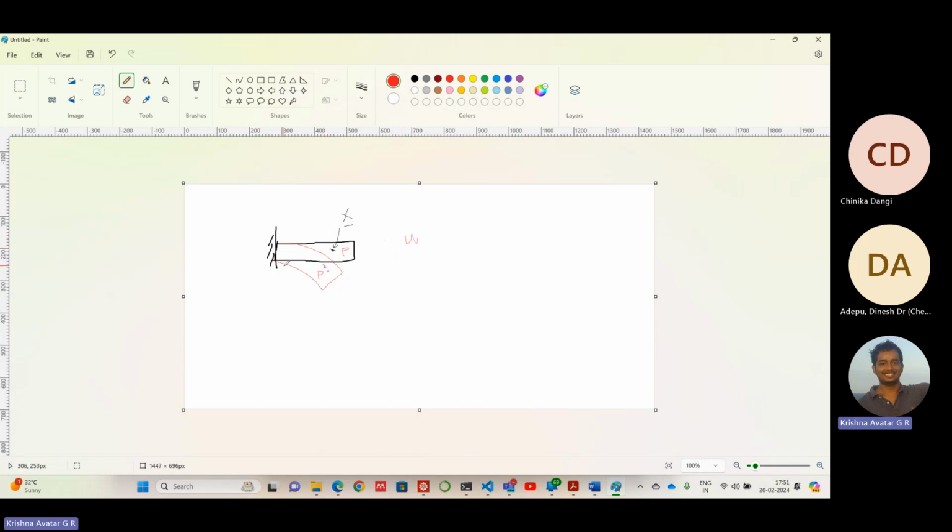The position vector of this in the Cartesian system will be x prime. So the relation between x prime and x is x prime equals x plus u. This u is the unknown. In the total Lagrangian formulation, we always work in the reference configuration, and our goal is just to compute u. So all the integrals, everything will take place in the undeformed configuration.